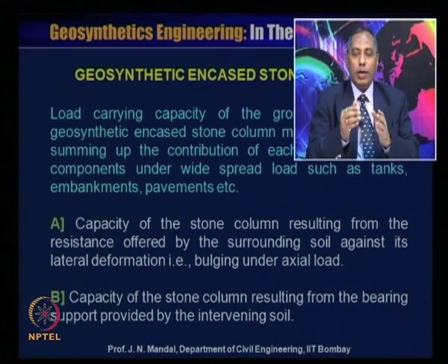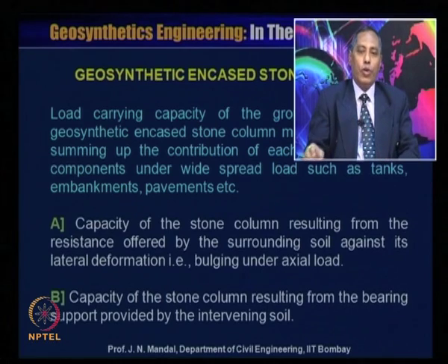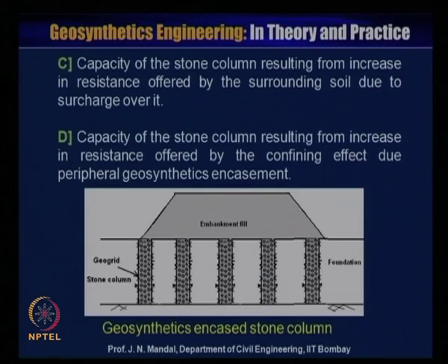B. Capacity of the stone column resulting from the bearing support provided by the intervening soil. And C. Capacity of the stone column resulting from increase in resistance offered by surrounding soil due to the surcharge over it. And D. Capacity of the stone column resulting from increase in resistance offered by confinement effect due to the peripheral geosynthetic encased stone column.